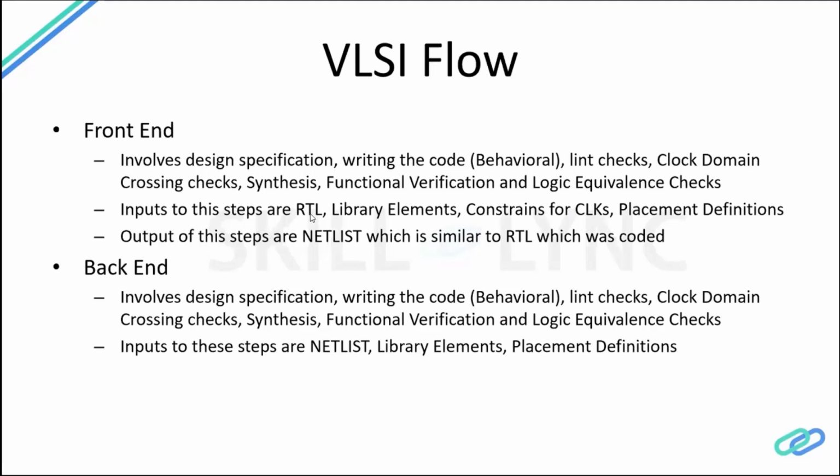RTL we give for lint checking, clock domain crossing check, and synthesis. So basically, all the front end steps need RTL for sure. Library elements are needed for synthesis and logic equivalence check. Constraints are needed for synthesis and clock domain crossings. Placement definition is needed for synthesis.